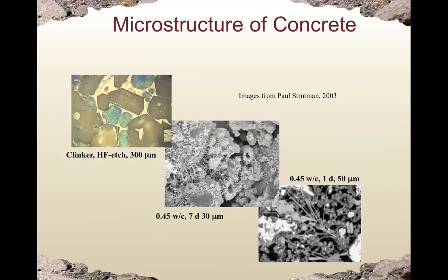We can also use image analysis methods. We can take a picture of cement clinker. So this is cement clinker, and based on the color and the shape of different compounds, we know, for example, this is C2S. The dark color round materials is C2S. The light color angular shape materials is C3S. And everything in between is a mixture of C3A and C4AF.